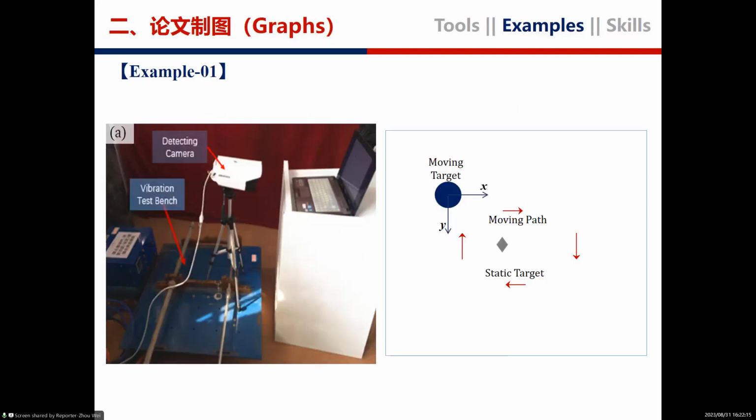The PowerPoint can do a lot of incredible things. For example, in this work, we have to validate that our visual detection algorithms work well, even if the camera is installed in a vibrating catenary supporting pole due to strong winds. In practical cases, it is impossible to perform validation tests. So we put a vibration platform underneath on which the camera is installed. The vibration frequency and magnitude is set according to what was measured in vibration on a supporting pole.